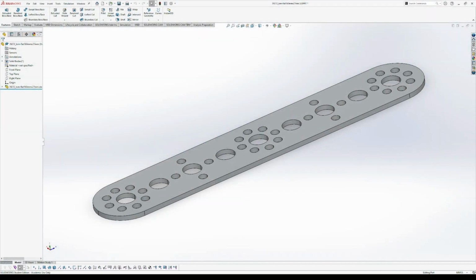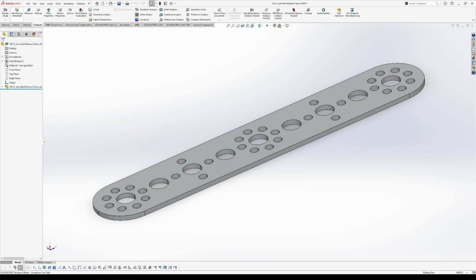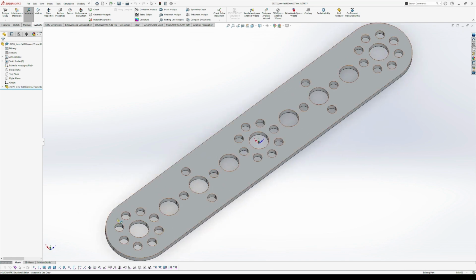This model is the same one I went over from the example earlier. It is a simple Tetrix plate with both ends bent at an angle to create one half of the claw used on the Gen 1 robot design. In order to make this claw, I looked at the SolidWorks model of the real unmodified version of the plate and used some measurements that I took off of it with the Evaluate tool, which essentially acts as a multi-purpose digital measuring tape, in order to replicate the original model's outer dimensions.